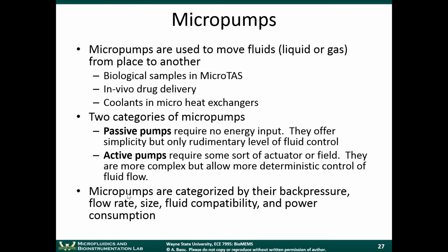A lot of times, you're limited by wanting to use the simplest thing possible. So folks have come up with interesting ways to do pumping that are actually quite simple. The most recent ones, which I'm not sure we'll get to talk about in this module, but the most interesting types of pumps now are the ones that just rely on paper. You put a drop of water on paper, and the water just spreads out by capillary action. Those types of paper microfluidic devices are used in a lot of lab-on-a-chip type devices nowadays.